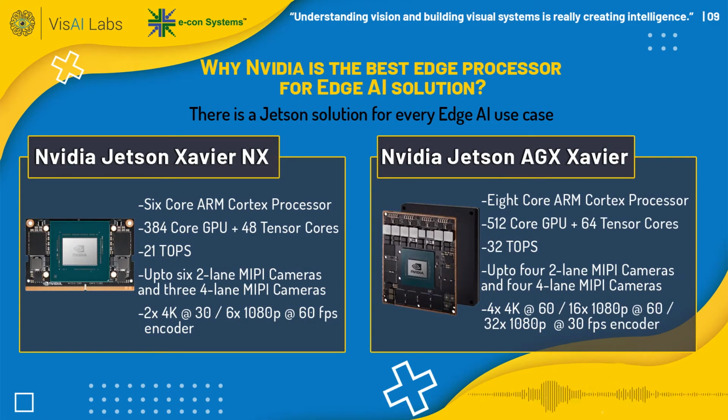Then the Xavier NX and Xavier are the most powerful edge AI platforms available today. The Xavier NX is one of the latest launches from Nvidia, which has a 6-core processor and a powerful GPU. Also, it has 48 tensor cores, which are specifically for neural network inference. And it can have up to 3 4K cameras and 6 full HD cameras, like Nvidia TX2. And it is pin-to-pin compatible with Nvidia Nano as well.